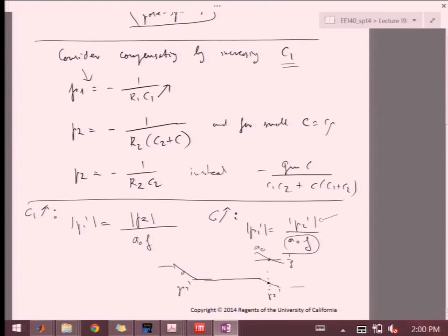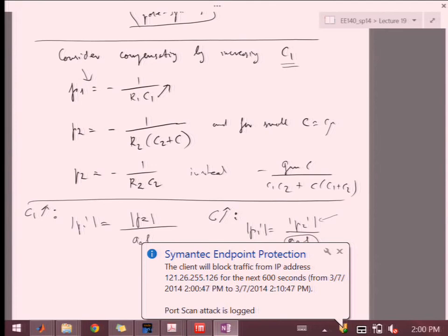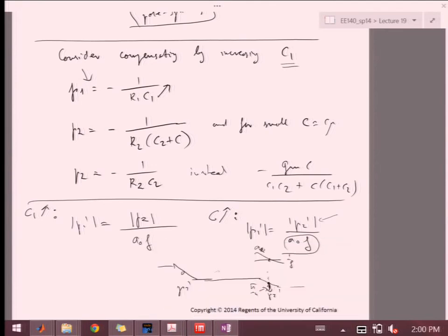This is A0, or A. And because of that, you always are guaranteeing pi over 4 phase margin right over here. Right? So it doesn't matter that I've kind of stretched this a little bit or shifted it in frequency. What matters is that I'm guaranteeing this phase margin here of pi over 4 by locking myself to the second pole.